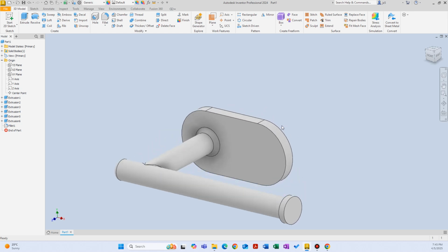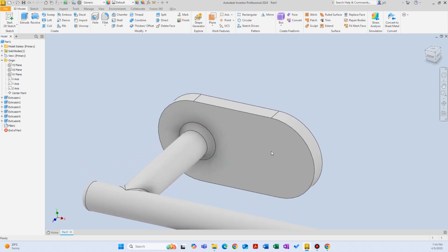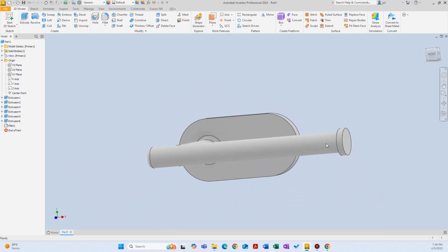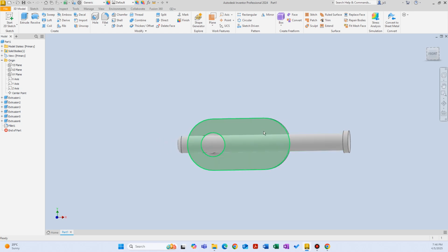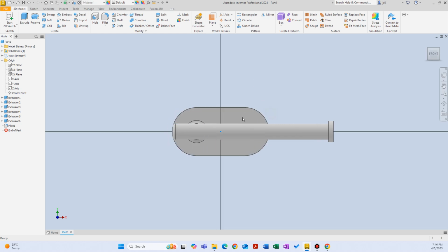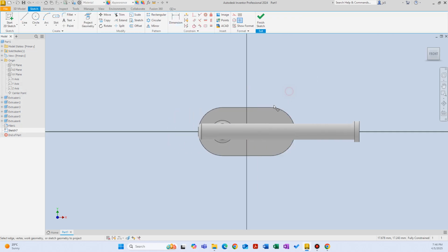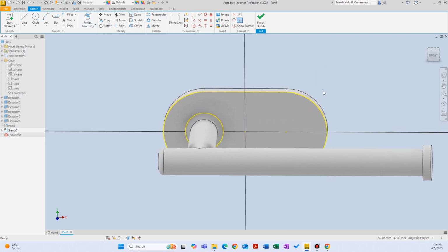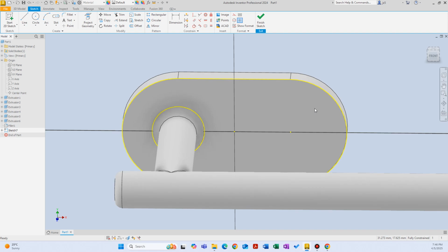But now the only thing we have not done is the mount holes, and we want to add some mount holes. And I'm assuming that I'm going to drill it like this, so I don't want this section to be in the way, so I want to be able to drill it with the power tool. So I need to probably add two holes, kind of on the top and the bottom of this base. So let's create a sketch there, project this geometry, and we don't have to, but let's use some